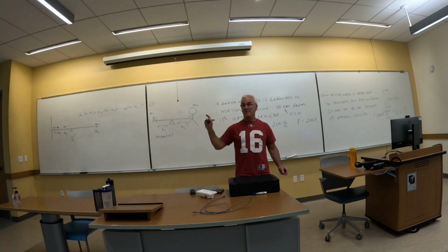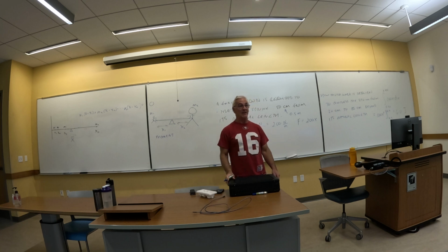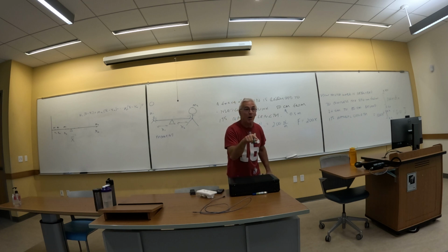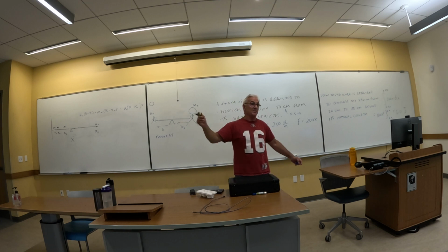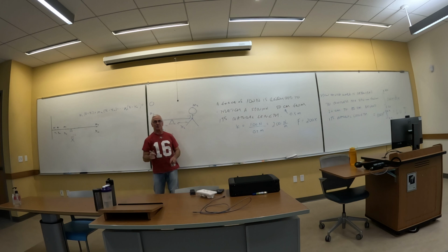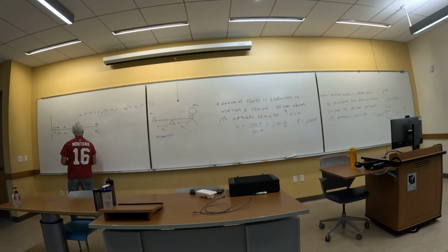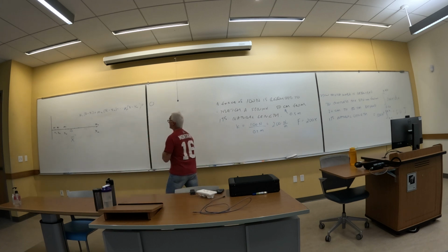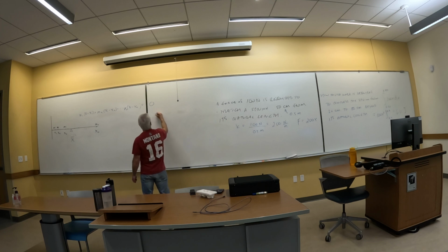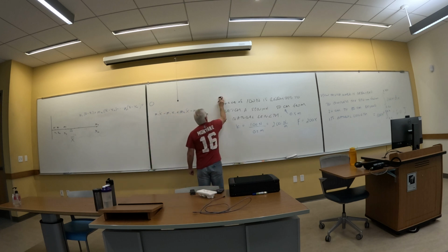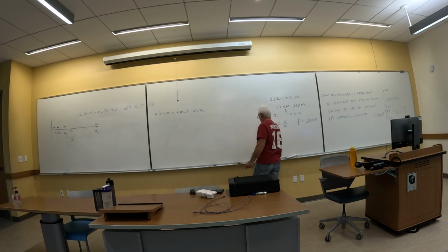If that x bar is exactly where it's supposed to be, then the moment on the left has to equal the moment on the right. But I don't know the value of x bar, so by adding them all up, I'm expecting half those values to basically be negative and cancel. If I knew exactly where x bar was, I'd say equals the other side, and I'd reverse the order of subtraction. Well, to set this up then, let's distribute. This is going to generate our calculus formula in just a moment, by the way. No pun intended. So I have m1 x bar minus m1 x1 plus m2 x bar minus m2 x2, and we'll go all the way to the end. Let's assume n is large.